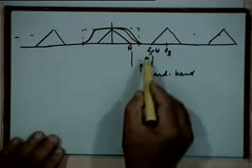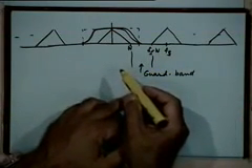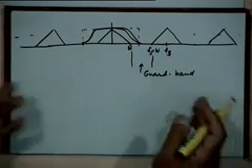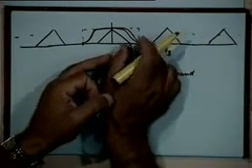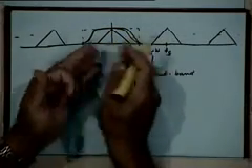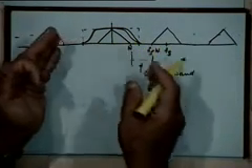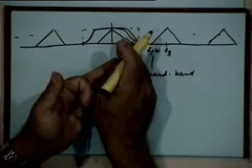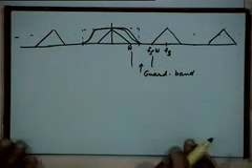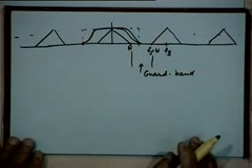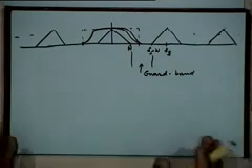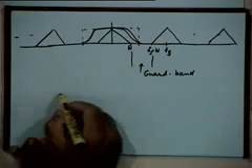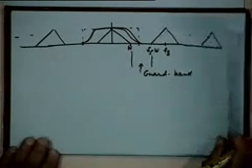The second thing is, if you do not provide for a guard band, a certain kind of distortion occurs, which we call aliasing distortion, because this lobe will now get merged with this main lobe and you will not be able to separate the two out. When you do a low pass filtering, some portion of the spectrum from the next lobe will also interfere with the main lobe, and your resulting reconstructed signal would be a distorted version of the original signal. But these are things that you already discussed in your sampling theorem, so I am not going into details of those. So that is as far as pulse amplitude modulation goes.